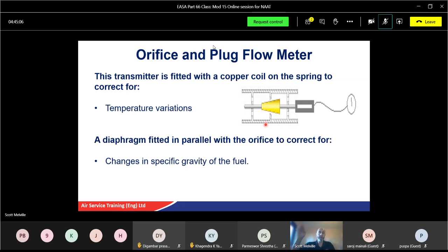So although it might be reading 30 kilometres an hour, you're probably doing about 40 kilometres an hour, thereabouts. And likewise, if you reduce the size of that wheel, you'll be indicating you're going faster, but actually you're going slower. Okay, so with these type of things, these account for those changes in sizes and flows.